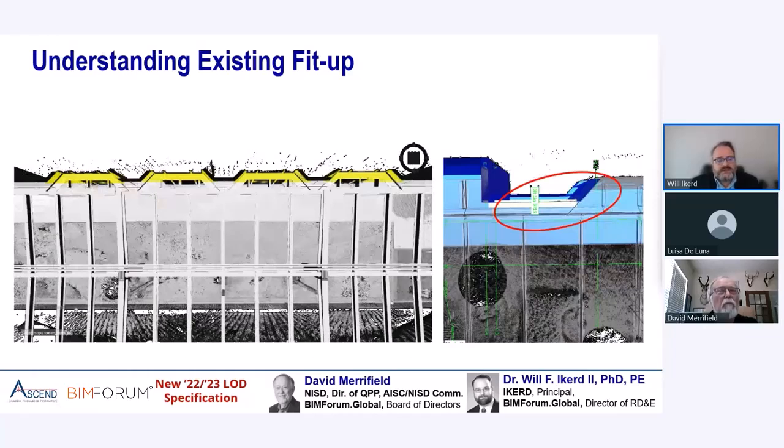What you're doing in most cases with most sets of LOD definitions, if you write the statement in your contracts that I want an LOD whatever model, you're asking for a unicorn that doesn't exist. A model's this cocktail of elements at different LODs. And particularly with laser scanning, from our research in interviewing teams, one of the things we see crop up often is when teams are mixing the LOD terminology with reality capture for scan to BIM.